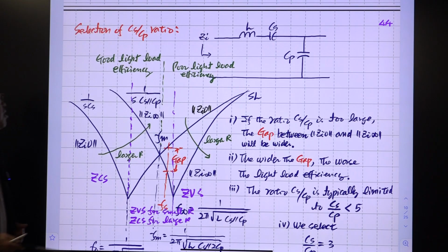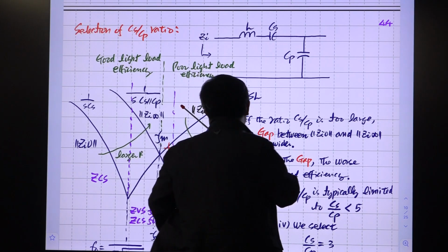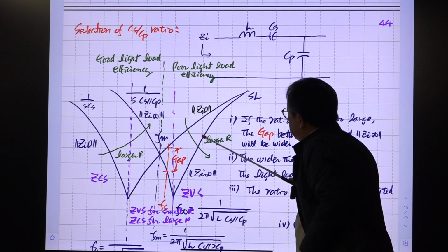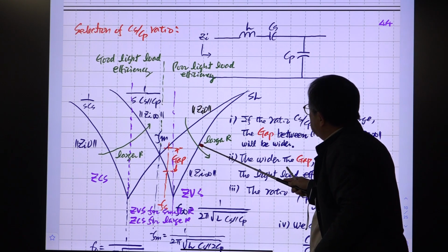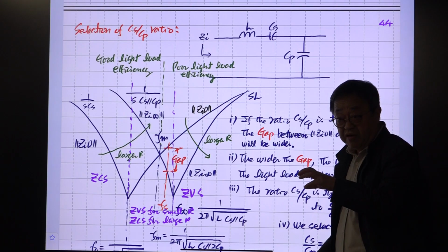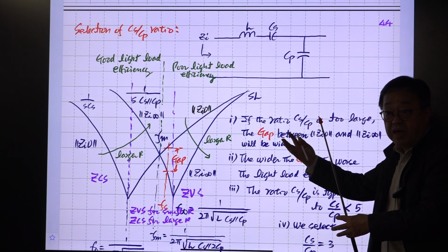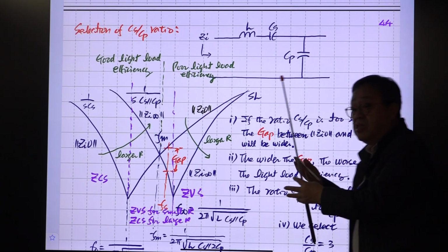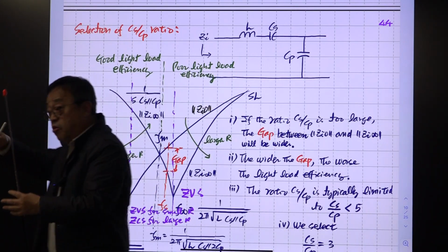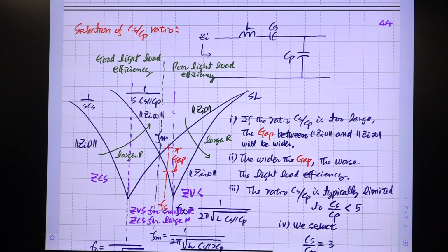In this region, you increase R, so the load current is decreasing, but somehow this input impedance is decreasing, then the tank current is increasing, right? So that is very bad, okay? The same case with open circuit condition: you are not delivering any power to the load. The same tank current is just circulating through the tank circuit and just consumes conduction loss.